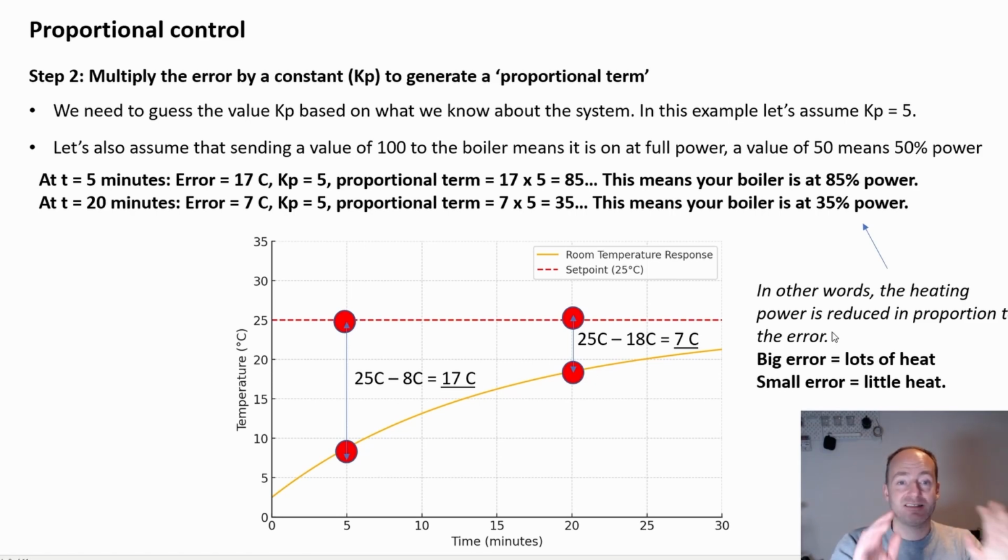So that is the essence of proportional control. The amount of drive signal you give to your heater is proportional to the amount of error you've got. The smaller the error, the smaller the heating. In an ideal world, when you've got no error, you've got no heating and you're perfectly at your set point value. If you drop below that set point value, you get some heating and that increases the temperature. So you should maintain that value indefinitely. Let's have a look practically how that looks and how we code it.